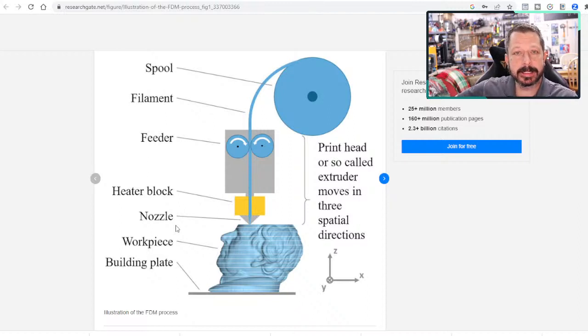What I would do is take a hair dryer, blow some hot air on those wispy strings, and they'll just shrink back up into the part, and you won't even know they're there. If there are minimal bigger strings coming off of there, you can just clip them off. But if you've got a whole bunch of stringing everywhere, then it gets cumbersome to try and remove it all, and you're better off trying to adjust your retraction settings.